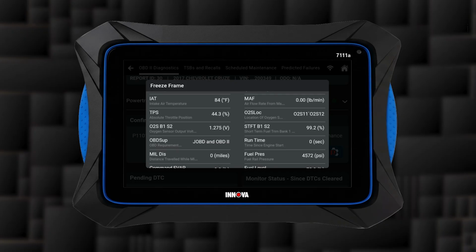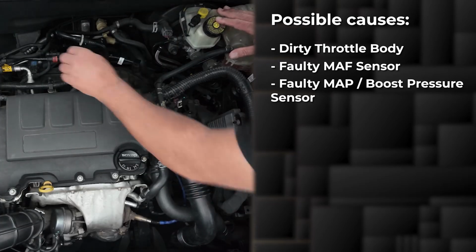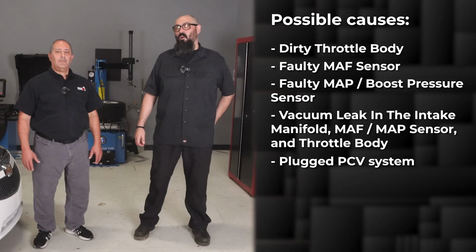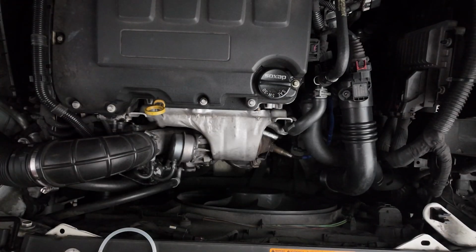Now, let's take a closer look at what could be causing this code. With code P1101, there are several possible causes, including a dirty throttle body, a faulty MAP sensor, a faulty MAP boost pressure sensor, a vacuum leak in the intake manifold, MAP sensor, or throttle body, or a plugged PCV system. There's a lot of things that could be wrong. So first we need to run a few tests to figure out exactly what's causing this code. Let's go step by step.